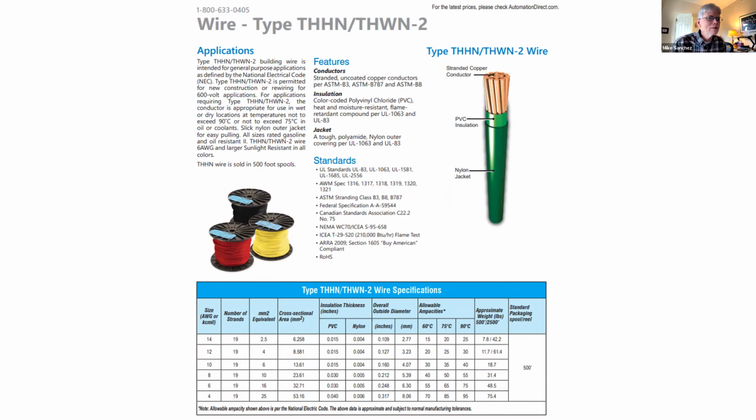THHN is very common. A lot of people have built their antennas from this, Field Day, whatever. And it does impact how the antenna behaves, and particularly its length at minimum SWR. And here's all the different THHN wire specifications in terms of its diameters, what you need, and all of that stuff. I separately had to look up the dielectric constant for nylon or PVC, which is all out there.